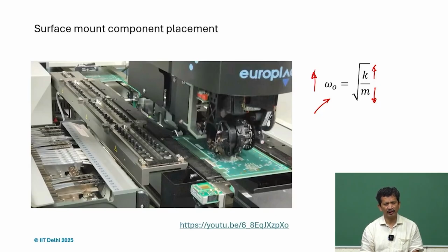We will also learn why loading in the axial direction is preferred over bending and torsion when it comes to achieving high stiffnesses. At the same time, when we are looking for compliance, less stiffness, where we want to get adjustment easily in certain directions, why we go for bending and torsional loads or deformations.